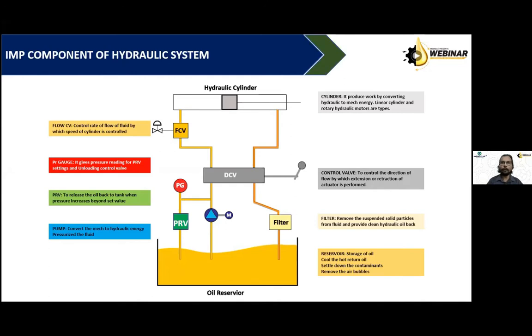So in due course of operation, the surface will get rough, the piston seal will get worn out, and the performance of the cylinder will come down. Instead of sealing the oil, they will start leakages or passing of the media, and later on we will come up with failure of the entire system.